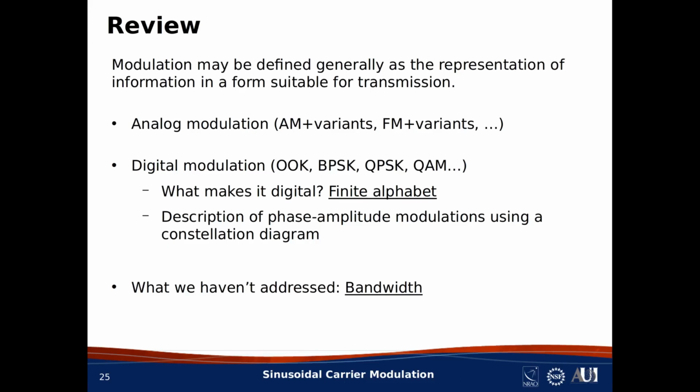That is, you limit yourself to M carrier states, and that's all you're allowed to use. You get a performance benefit because the receiver knows in advance that it's looking for one of M possible things, as opposed to a continuum of possibilities. Finally, we've just started to touch on the topic of bandwidth, but we haven't properly addressed it yet. That will be a topic for another lesson. However, you can anticipate that bandwidth will depend on the type of the modulation and also the rate at which information is sent.